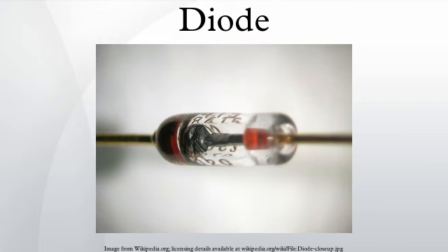Current-voltage characteristic. A semiconductor diode's behavior in a circuit is given by its current-voltage characteristic, or I-V graph. The shape of the curve is determined by the transport of charge carriers through the so-called depletion layer or depletion region that exists at the PN junction between differing semiconductors.